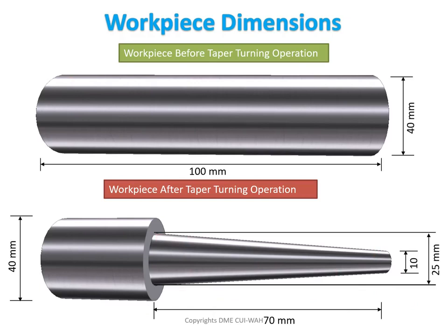In the last slide, I think I missed the word of taper turning. So you can see from 40 mm to 25 mm, this is step turning, and from 25 mm to 10 mm, this decreasing dia uniformly is the taper turning. This process is taper turning.